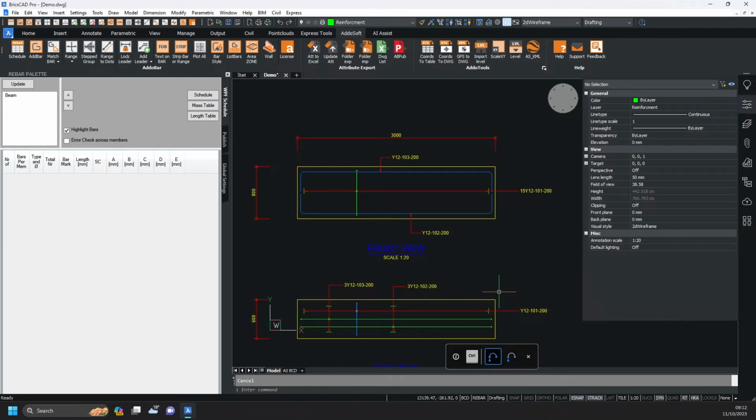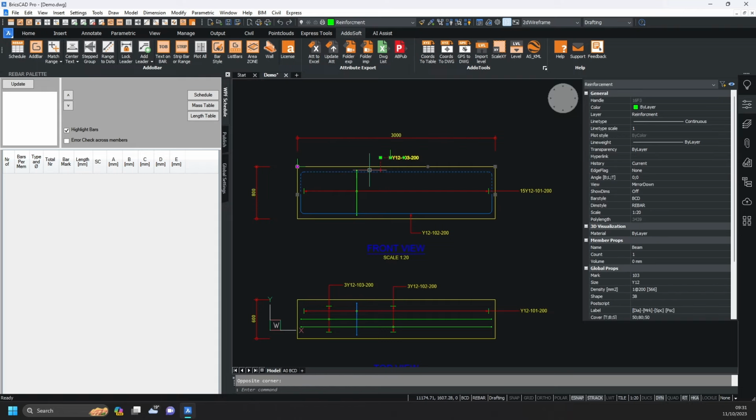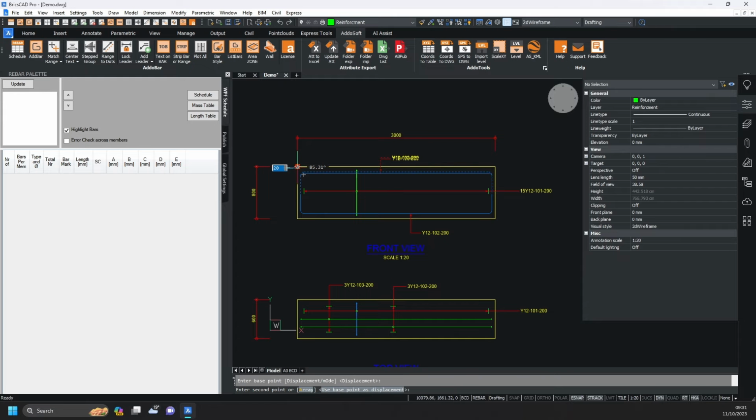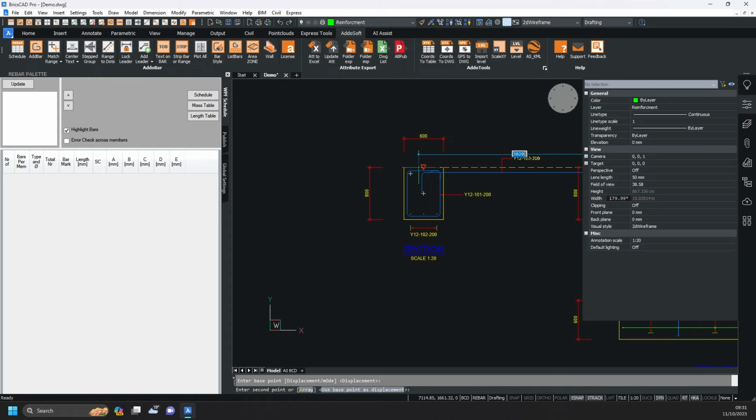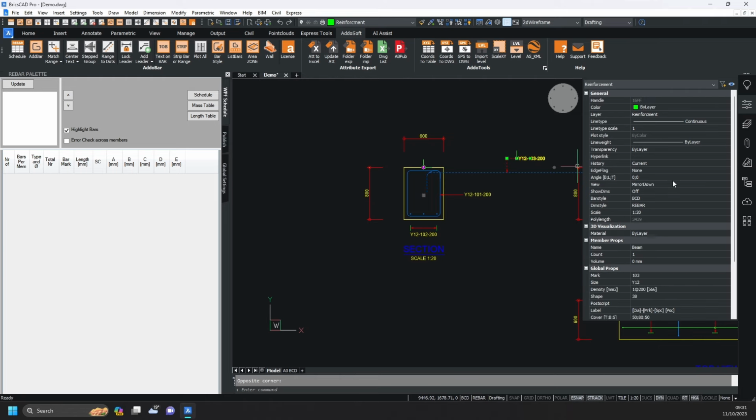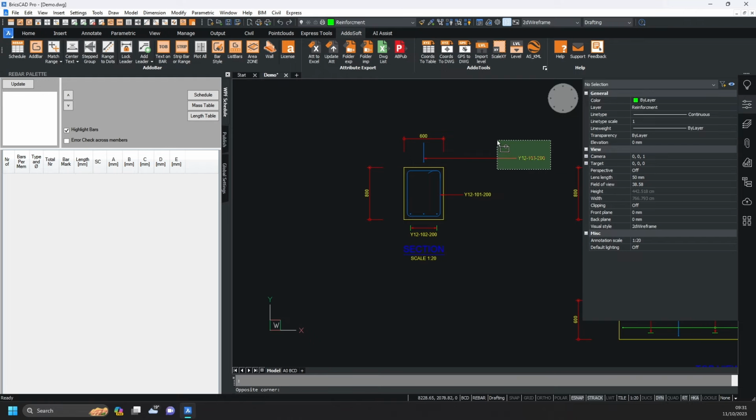range line. Let's add the dots again in the section view by adding the range as previous. Copy the bar in the front view to the section. We can then change the view to side. Just a note on the leader. It will be automatically removed and re-added when we call the range command, so we don't have to worry about the current placement of it.